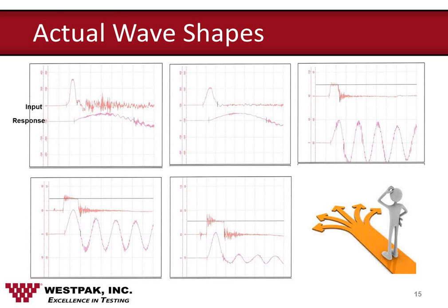We'll also notice that the phase shift between the response and the input has become less and less as the input pulse duration increases. This is another way of saying that the spring mass system can respond to the shock input better as the input becomes closer and closer to the natural period of the spring mass system. The remaining plots show that the response continues at this max response level as the duration of the input continues to increase.